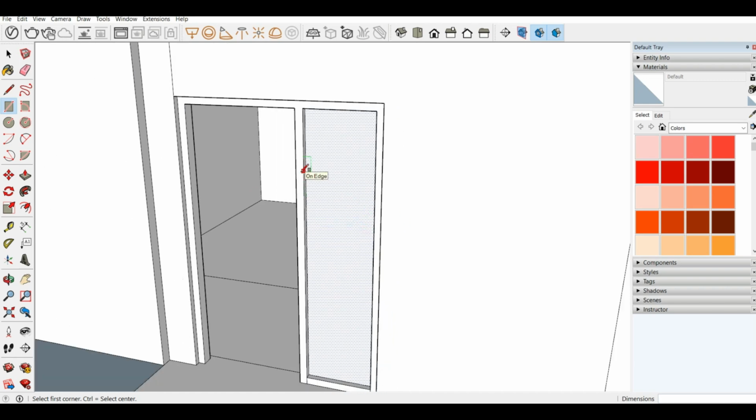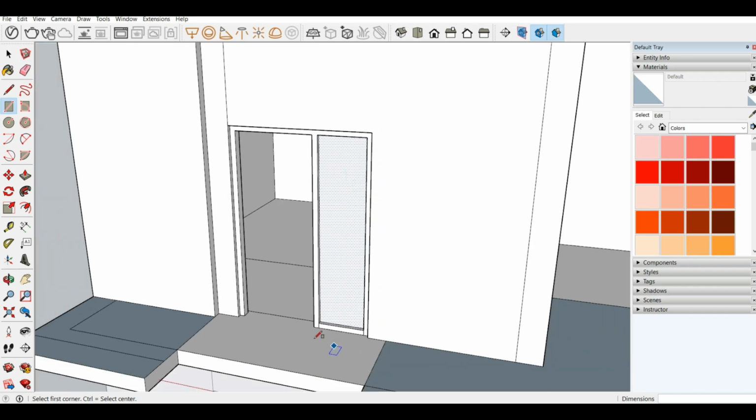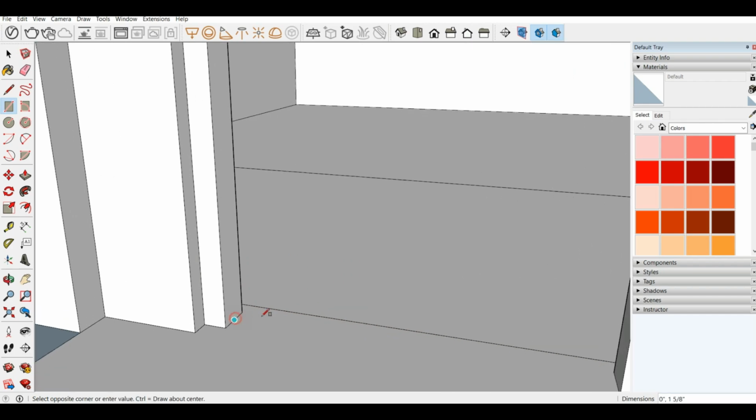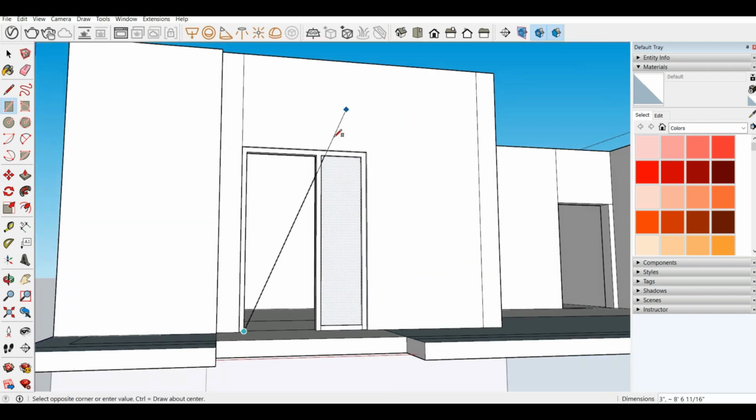So now you might be thinking why we do this reverse face thing. So the blue color you are seeing is probably the back face color, so the white is the front face color. So if you have a cube, all of the outside faces should be white and the inside faces should be blue. So we need the front face, of course, so that when we apply some materials later on using V-Ray, there isn't any problem during that process. So this is why we do reverse faces.